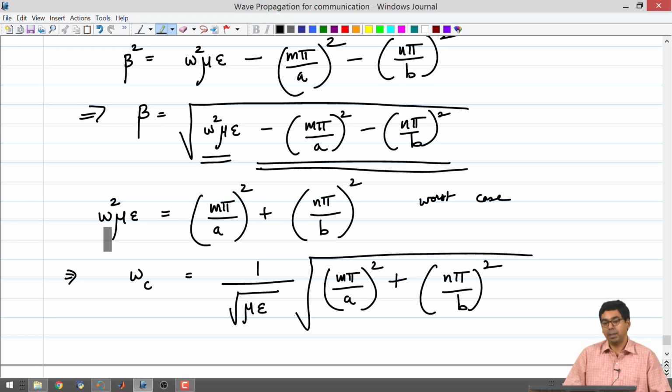It is a very important thing, because if the waveguides have two plates and you have vacuum or air filling it, we already know from our prior classes that vacuum or air is a non-dispersive medium. But if you make a waveguide out of it, suddenly it becomes dispersive, that is, it will have different values of velocities for different frequencies. So, omega divided by beta, d omega divided by d beta, all these things we will be seeing in the next class.